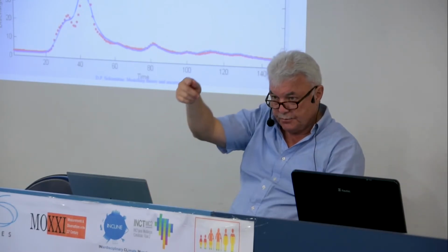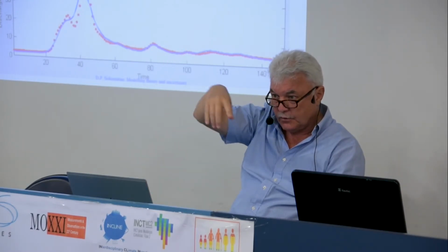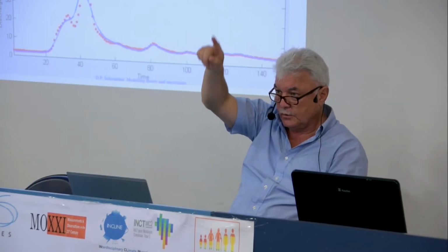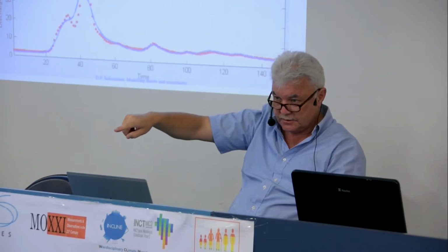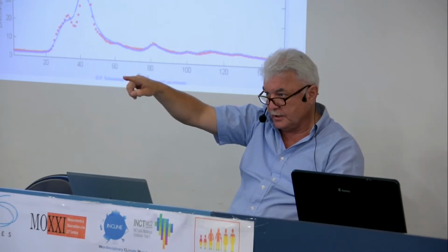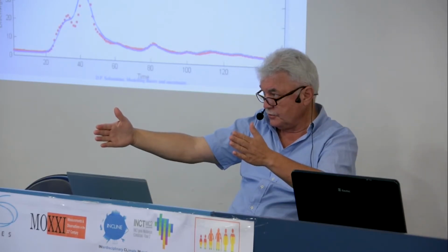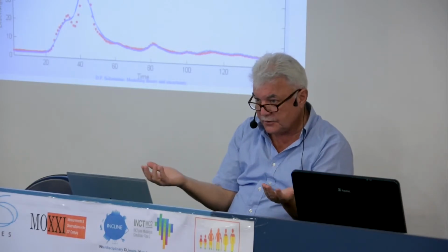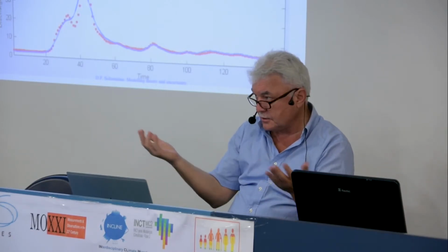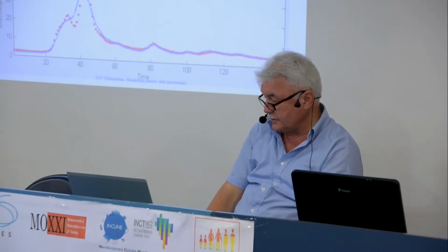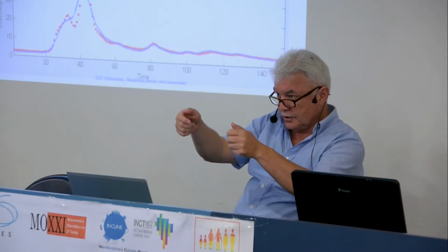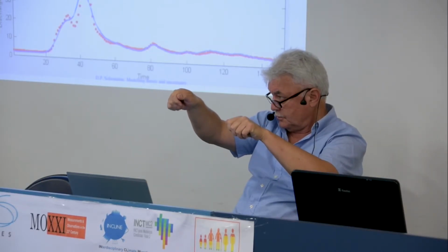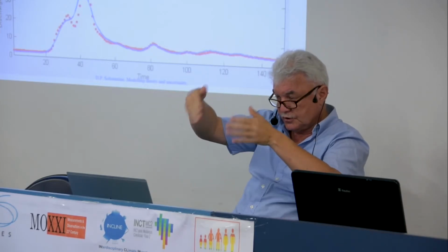Or you pick up the standard Brazilian rainfall. In Holland, for example, rainfall has often two peaks. Big peak and then small peak returning, and length is known. So there are models of rainfall generators. You can find literature on rainfall generators. There is a very well developed science of this. So rainfall generators allow you to introduce randomness into this, and you just sample these parameters.